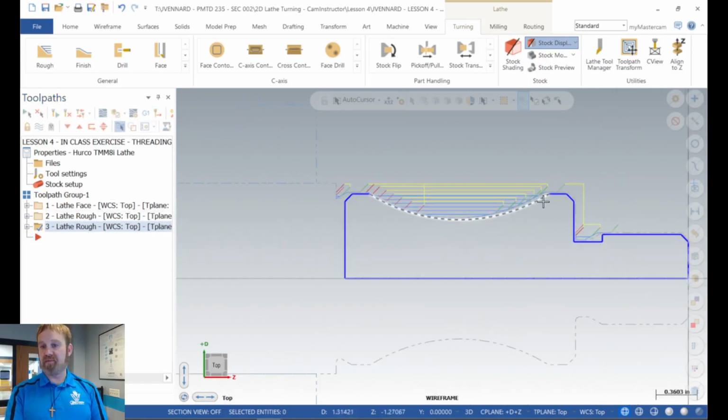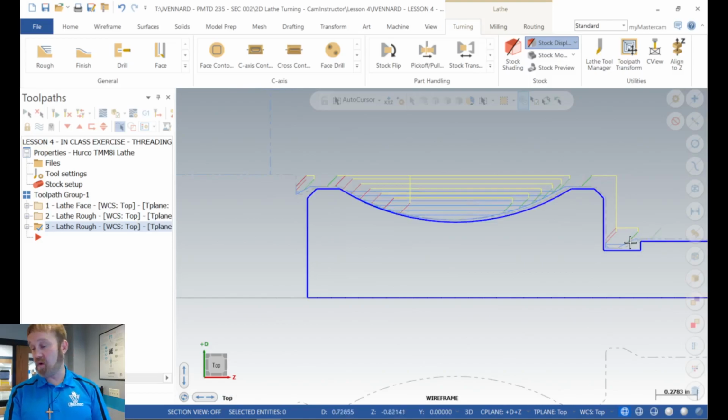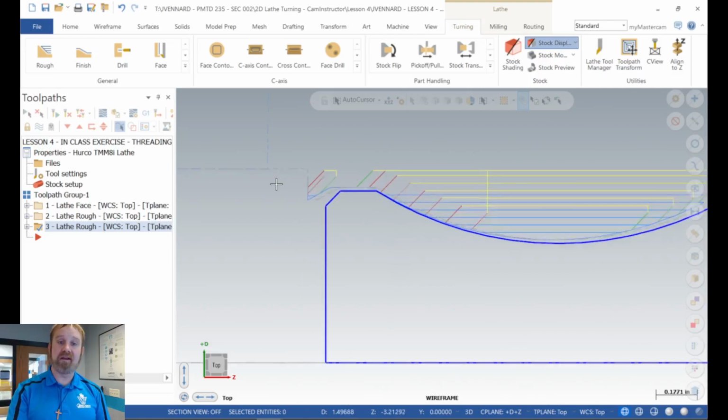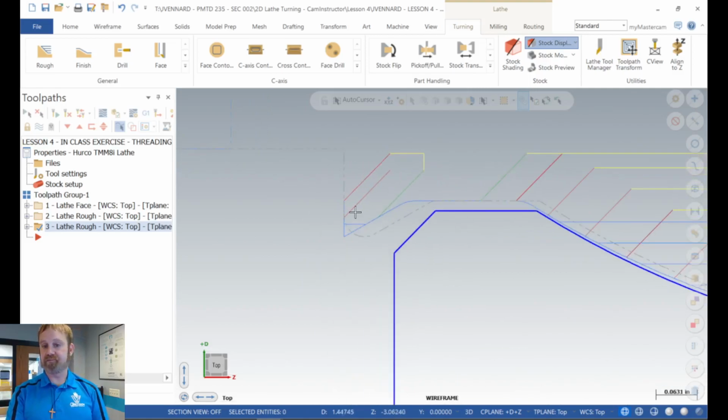Now, since it's aluminum, like I said the other day, I'm not real worried about the aluminum trying to dive down into these areas. I'm okay with that, but I do have a problem with one thing back here. I'm not far enough past the end of the part. With the extension that we did here, when it gets back there and goes down at 45 degrees and I extend it 130, it's extending that out 130. So it's really kind of like a 45-degree triangle. It's only going about half the amount that I need it to in Z on that first pass.